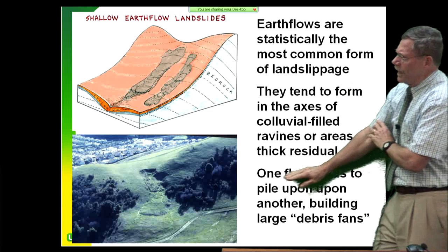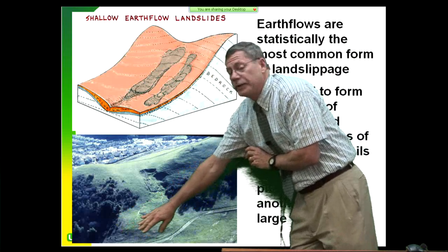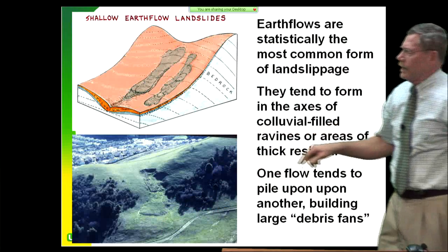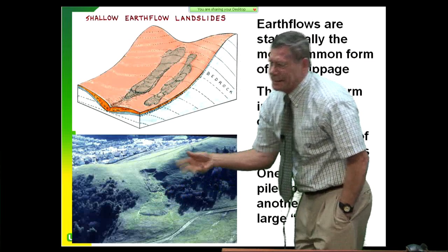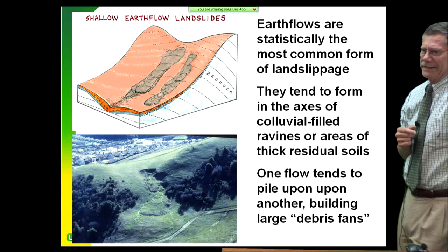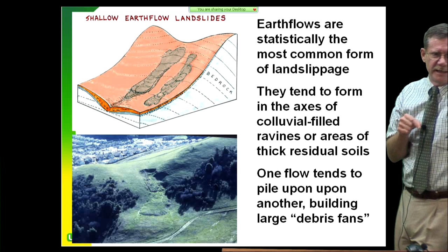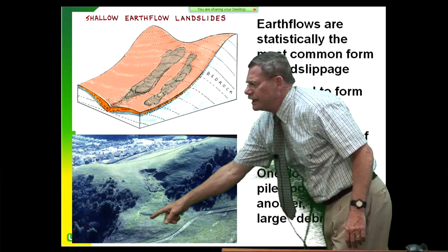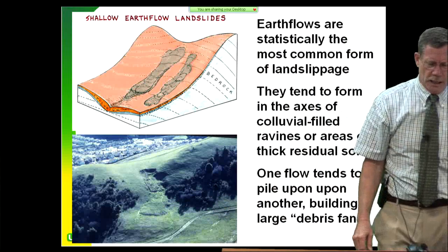Yeah, so you can put the highway in here, but on this section, we had to use a bunch of mechanically stabilized embankments. We had to do a lot of over-excavation. We had real problems because guess how wet this stuff was? Moisture content was all in the 40s, above 40%. Optimum moisture was 15. So that's a lot of microwave drying you got to do to get that soil dry enough to be able to compact it to something. Yeah, this was very, very low density, high moisture content. Basically what you guys would call junk, mud.